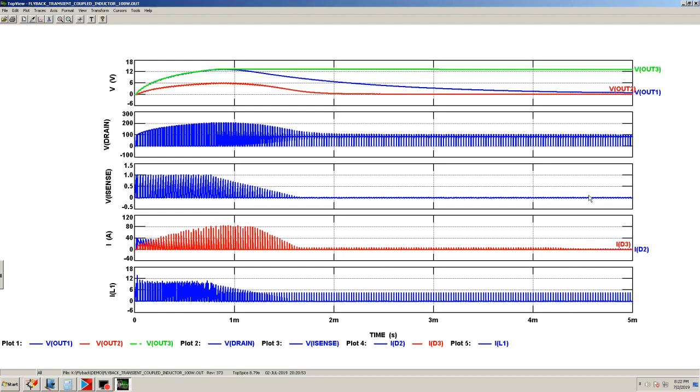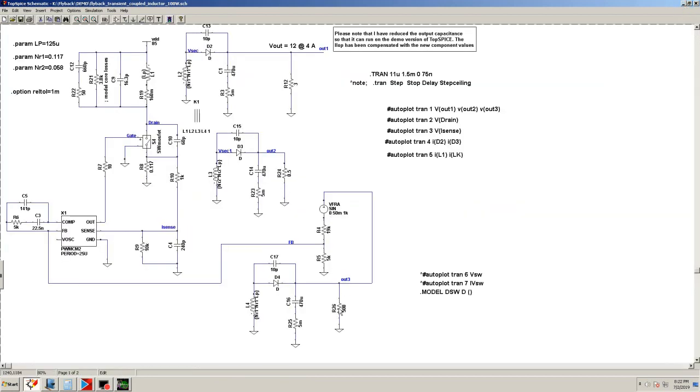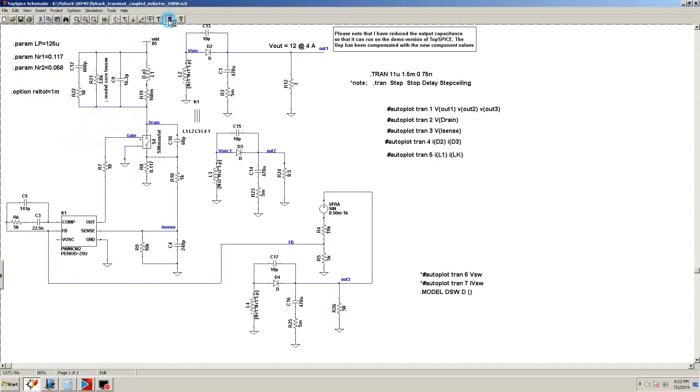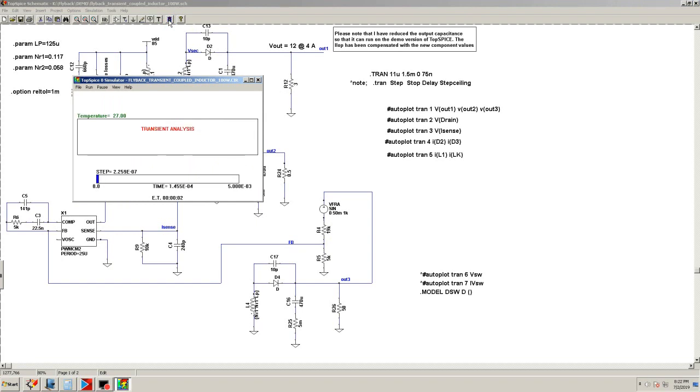So the duty cycle actually goes down, and it doesn't allow it to, because it's closed on this one. See, so that's very interesting. So let's go ahead and see. So basically, since this is lightly loaded, the PWM is reducing the pulse width to a bare minimum, and it's starving these windings. Okay.